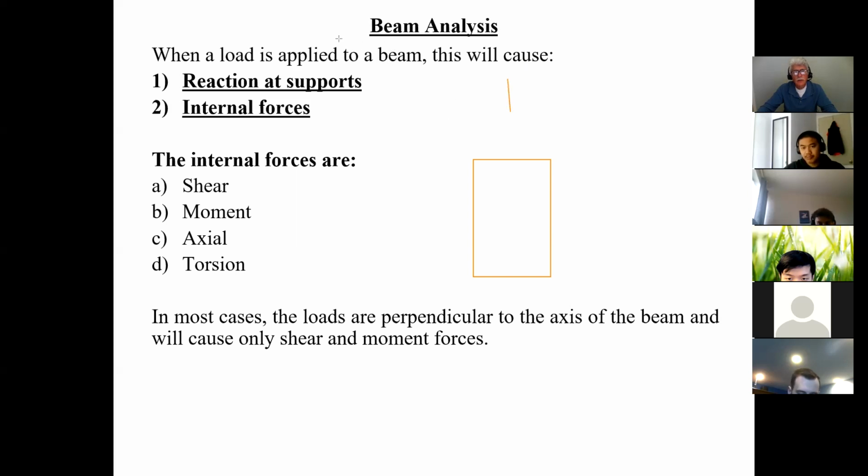Oh, I should have, hold on a second. Okay, here's my load. Here's a load I'm putting on the beam, okay? Now, when I put that load on the beam, I should have moved this over, but sorry. Now, you're assuming that that load is being applied. I should have drawn it a little bit more accurately. You're assuming that that load is being applied right where the center of gravity is of your member, okay? That's what you're assuming. In other words, this load is being applied right at that point.